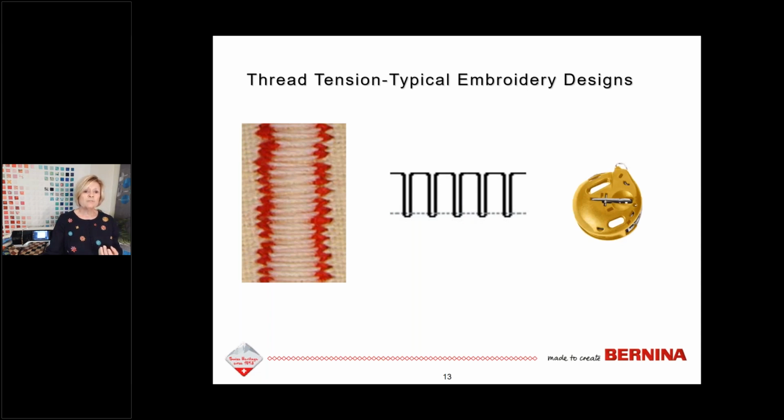The top tension is actually looser or being pulled to the bottom. Now, when you're doing typical embroidery, if you're not getting these results due to the fabrics, the threads, or perhaps the stabilizers that you're using, and you're on a BERNINA 5 or 7 series machine, you can use a high thread tension bobbin case, which is the gold bobbin case. Now, this bobbin case is set to a higher tension, which when embroidering will help to pull those threads to the back of the project, so your result is as pictured here.